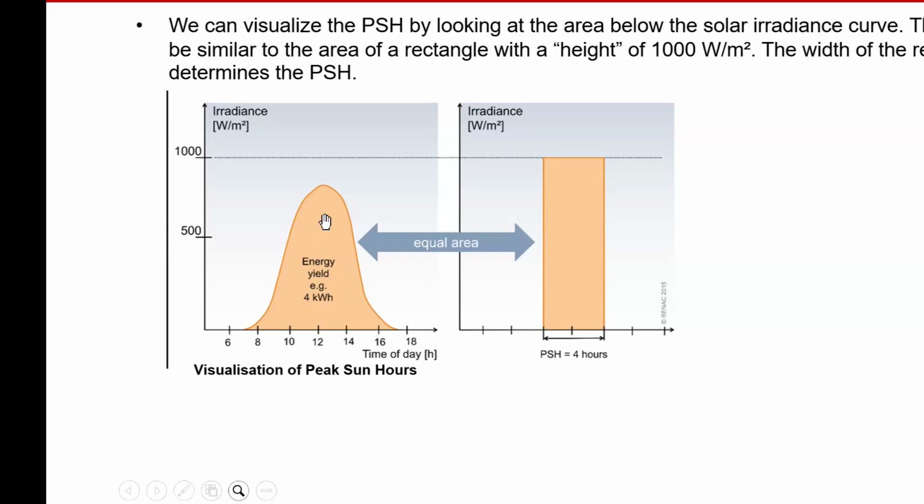So when you compress all of this, the height will increase further, but the length will now compress. This is what you're going to get. And when you do this, you're likely to get about 4 hours. So in Nigeria, peak sun hour is between 4 to 5 hours. If you go above that, then you're being overambitious. If you're going down south, it moves around 4 because of the kind of weather. If you're going up north, from the middle belt up north, you can increase to about 5 hours. So that's essentially what peak sun hour means.